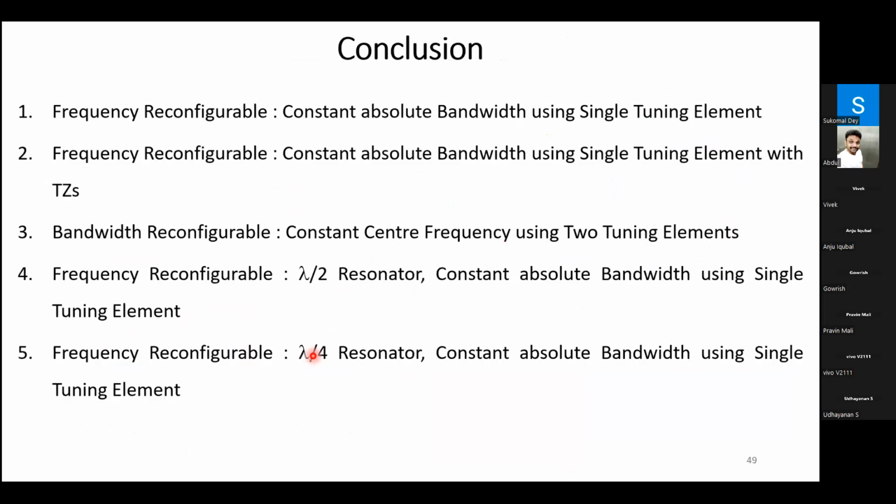So coming to the conclusion, I have presented frequency reconfigurable filters in both waveguide and coaxial technologies using a single tuning element. As I mentioned, that was a bottleneck, and we were able to solve that bottleneck. And I have also presented the bandwidth reconfigurable filter with 2 tuning elements.